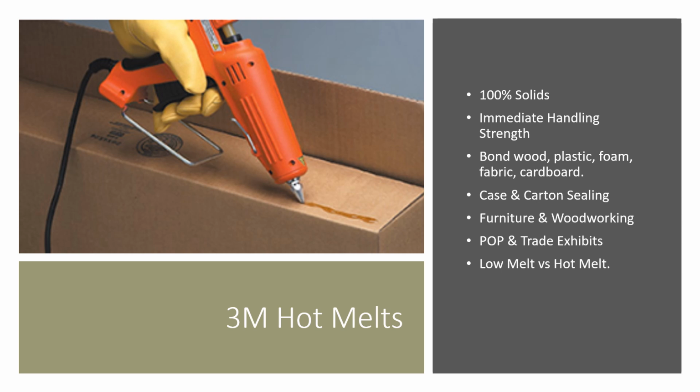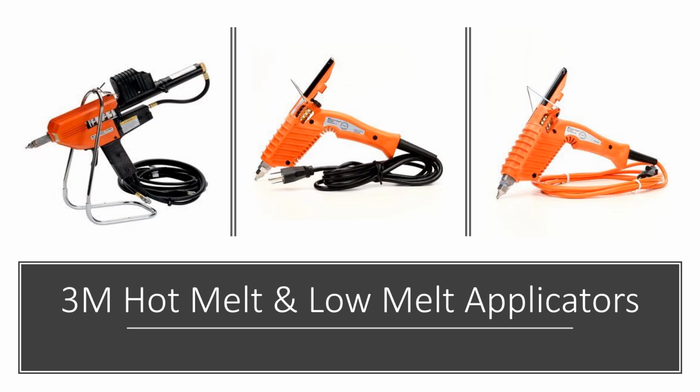And then there's some options for low melt versus hot melt. Low melts are dispensed at a lower temperature than hot melts. So if you're working with heat sensitive materials, it might be better to look at a low melt option. So 3M has a couple different types of applicators for low melts and hot melts, depending on the different size that you get the sticks in. There's longer sticks, shorter sticks, pellets. So these applicators are specific to the size pellet that your customer is looking to use. So, high volume, medium volume, low volume.